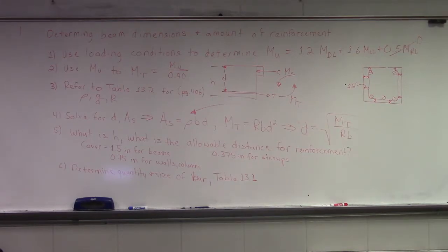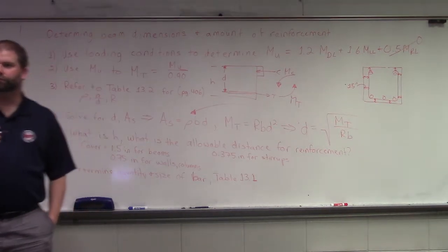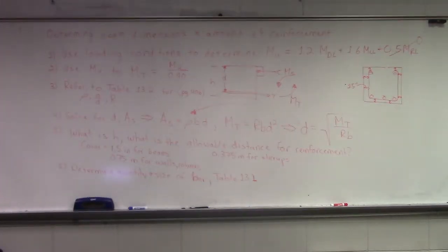Sizing your bars and your separations, and we did the one where there's too much space between them. What is acceptable, what isn't acceptable? We were saying, if you want the big members, there was 3 inches in between them or something. Yep, and now we're considering it unreinforced. Correct. Are we supposed to make that 1.5 inches, or what is your goal? What's your allowable? So it's going to depend.